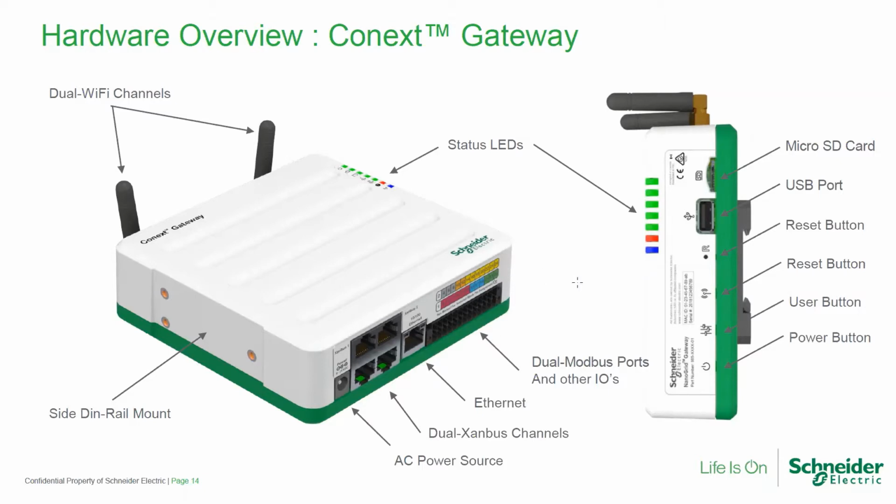A number of Schneider meters have been paired up to the gateway, so you can have metering around your system, both grid metering and load metering. You can also communicate with RS-485 devices such as string inverters if you have an AC coupled system. And you will communicate with your batteries, depending on your battery supplier, using this plug with RS-485 or CAN connection, depending on what your battery manufacturer has.